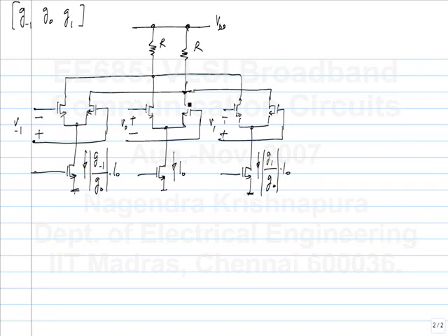So why is this a concern? The input capacitance of the circuit will also be smaller. So you have to drive a smaller load, so Nmos is better. So typically you tend to use Nmos. Again, we go to all these techniques to work at higher and higher frequencies. So at the highest of frequencies, you do use Nmos. You can always use Pmos, but you use Nmos if frequency is a constraint. Okay. Use Nmos at high frequencies.